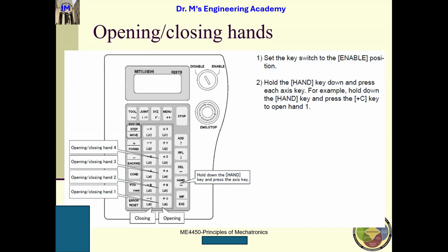So manually, how can you close your hand? Here is the hand key. If you press the hand key and the positive 0 simultaneously, the hand opens. I want you guys to write this down. If you press the hand key and the minus 0 simultaneously, you close the hand.